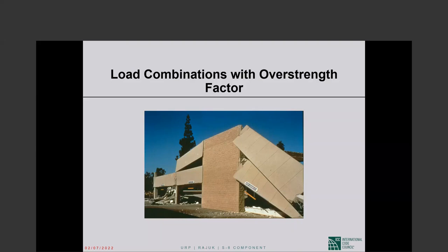the shear walls didn't have to do anything during the earthquake. And when you don't have to do anything, it's easy to look good. The shear walls didn't have to do anything because the collector elements that were supposed to deliver the shear to the shear walls failed before the delivery took place. So from that point on, this was 94, 97 UBC, we already required collector elements to be designed using what we used to call special seismic load combinations back in those days.